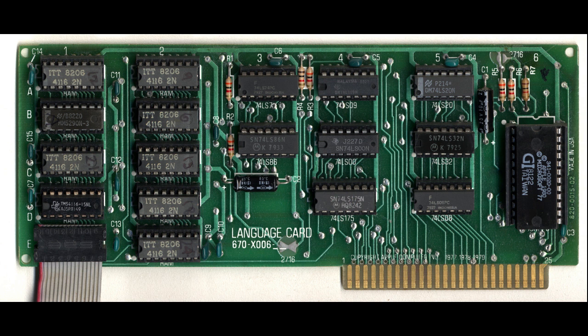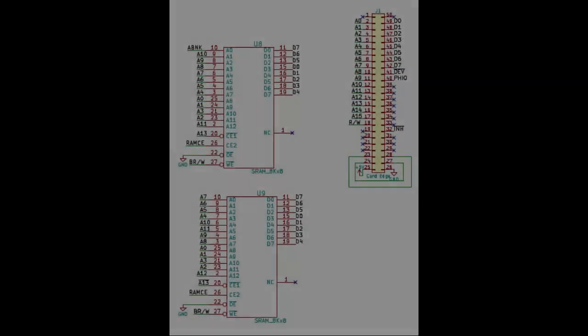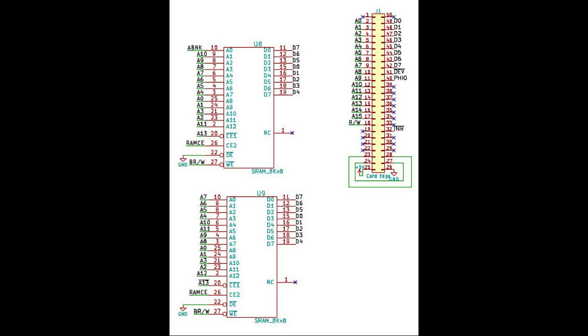And the board with static RAM, that is what I used, can be made with currently made chips and SMD chips too. And it takes only 2 chips to go to the 16 kilobytes. It doesn't need any pickup of refresh signals from another socket on the motherboard. All the needed signals can be found on the expansion connector, as you can see in the part of the schematics that I drew for my expansion board.